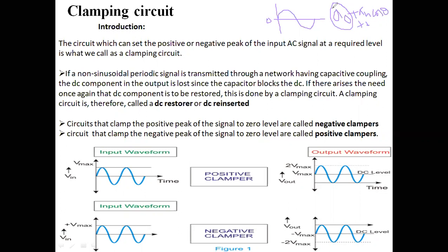Especially when we discussed the high pass or low pass circuits in the first chapter, for a square wave input, I said that if the time constant is very large, the output will be equal to the input for the high pass circuit. I am simply recalling the high pass circuit. You may get this type of waveform as the output. If the time constant is very large, the output may be equal to the input, except that the DC component in the output is 0. I had mentioned that point there.